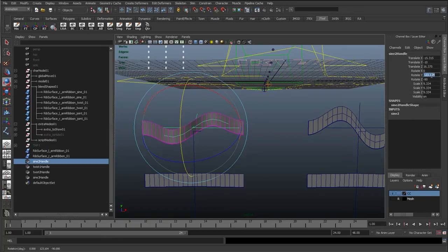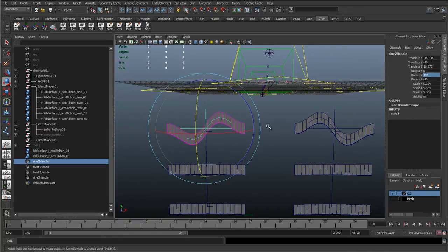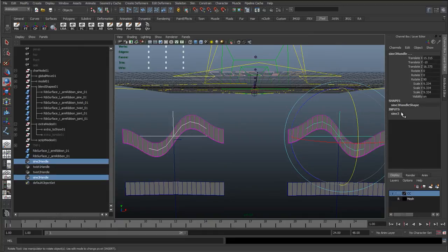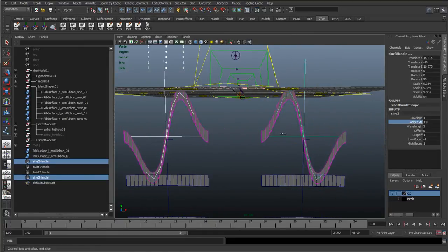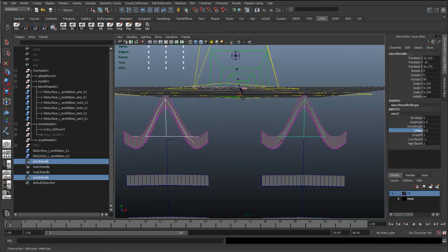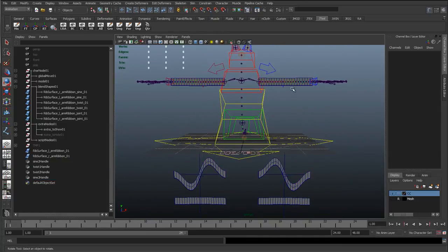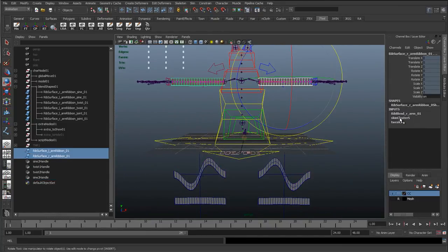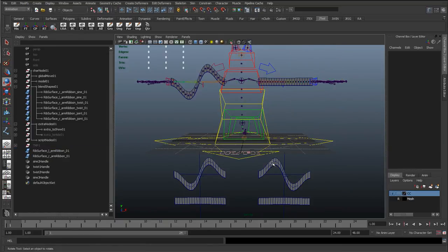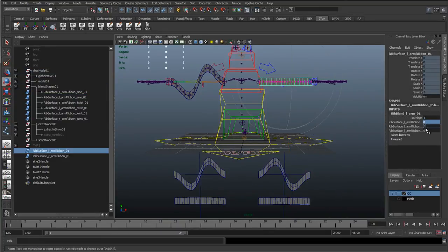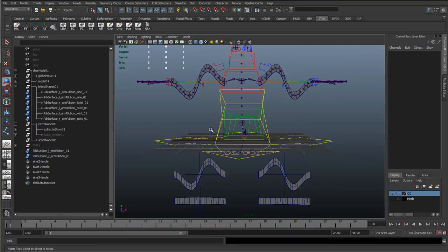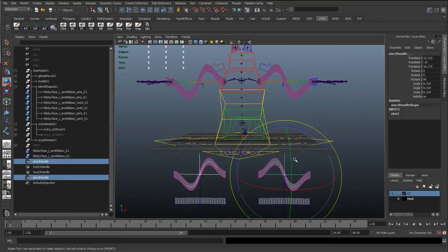So if I rotate this 180 degrees, I can get it so on both sides, both these arms, we're getting the same value. So we want to get it to mirror across basically. So on both sides we're getting the same waves, and that just looks really funky. And one thing at this point what I want to do is just select these two up here, go to the blend shapes and set all these to 1. And the same on this side, set all these to 1, just so we can see these working, so we can check that it's working above as well.